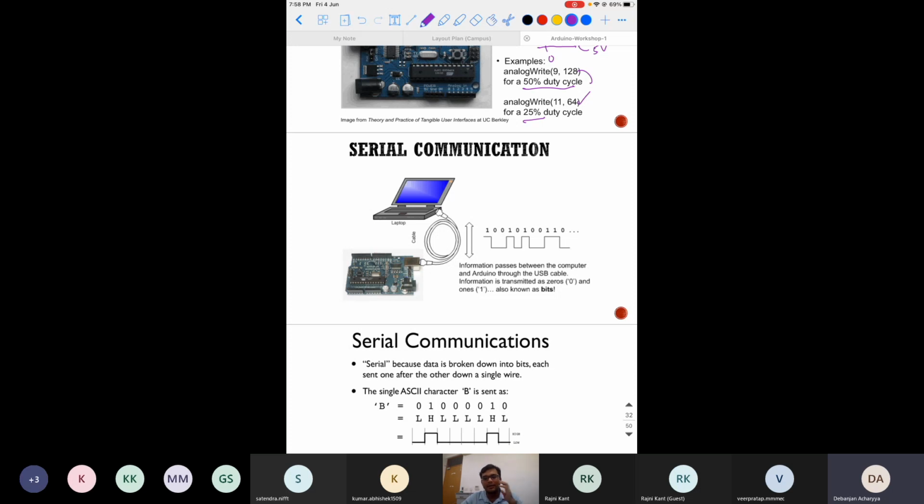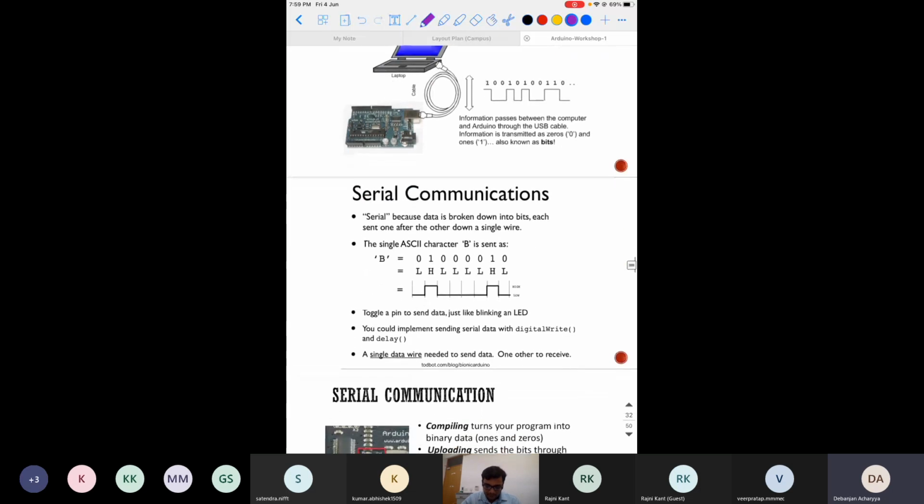There is a terminal. That terminal is called the hyper terminal. By using that hyper terminal, data acquisition is possible. Along with your software, that IDE 1.8 version that I have shown you, you have a side by side terminal window. By that window, you can take data, whatever data is coming from any sensor value or anything else, through the Arduino board. You can save it in your computer or any cloud. So I will show you that.